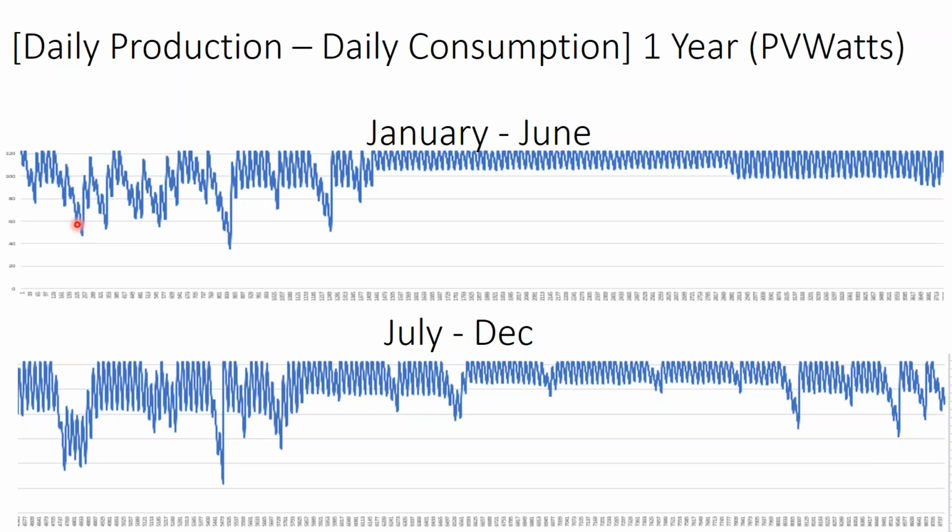That's going to be a problem whether you have a 22 kilowatt array or an 18 kilowatt array. On an overcast day, you're producing 20% of what you would under full sun. So sunny days are no problem living off grid. If you double your array size, you're going to get twice as much energy out of it, but that's still only 40% of what you would get under an array half the size on a sunny day. So it is, in most cases, kind of a waiting game to see if you can tough out the overcast days and really recharge on sunny days. Sometimes you need a generator to step in.